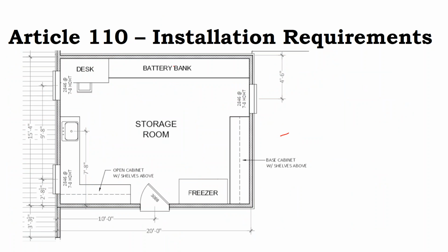But we say, all right, well, one problem is, I have an 8-foot long battery bank. So here's 8 feet, but it needs to be accessible. And so depending on my watering system and my equalization, you're supposed to be testing every battery cell as part of your maintenance. Maybe it's a maintenance-free battery. And if it's a maintenance-free battery, it can be shoved up against the side of that wall.